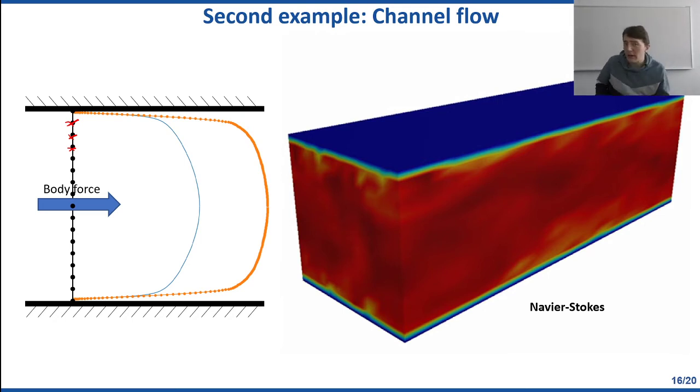And I didn't do anything wrong per se here. I used a right element pair, what we talked about in the previous slides. I used the right kind of stabilization for the advective term, I'll talk about that later. I used the correct turbulence model. So I did everything correct, and still I'm getting this 50% mismatch between what I'm obtaining from my computational solution and what it should be like. Now that's a pretty big mistake.